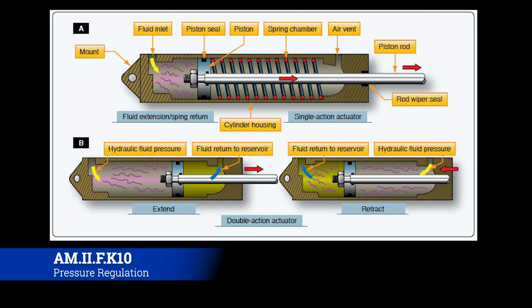It's been a minute since I worked on them, but either way, they have 3 double action actuators that will extend and contract in both directions equally, and that allows you to manipulate the flight controls of the helicopter with a lot of ease. If not, you'd be just fighting with push-pull tubes, and you wouldn't be able to fly very precisely. Matter of fact, it may very well be just unsafe altogether.